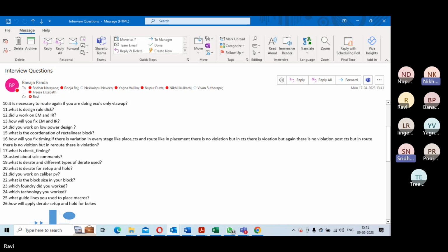So DRC is basically all the manufacturability rules, right? Whether it is spacing requirement, minimum width, minimum space, so that all that can be implemented properly. The fab gives you manufacturability rules to specify how things have to be done.